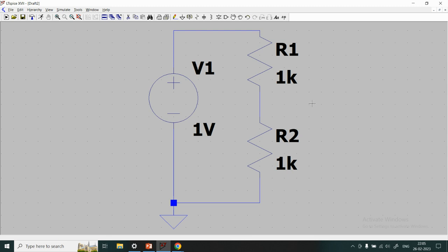Once that is done, what I can do, I can right click the net. When I do so, I have these options. So highlight net, label net, or delete the net. So I will click highlight option, the net will be highlighted. Again, I hit the escape button on the keyboard. I come back to original position.